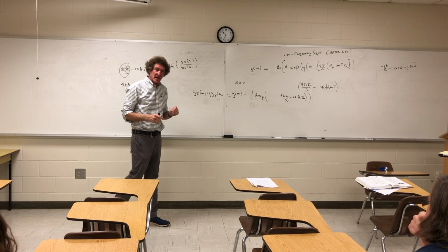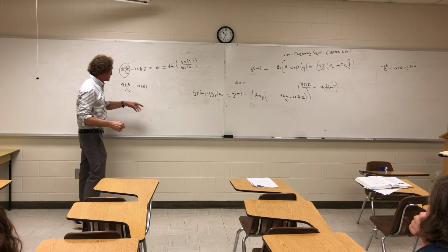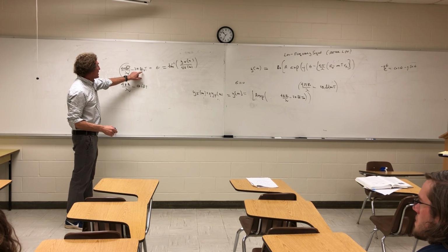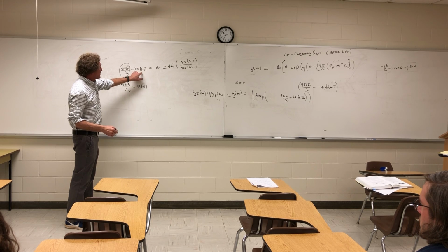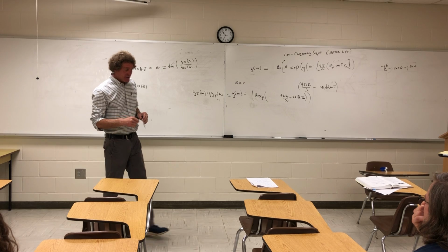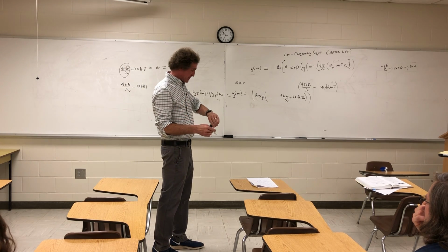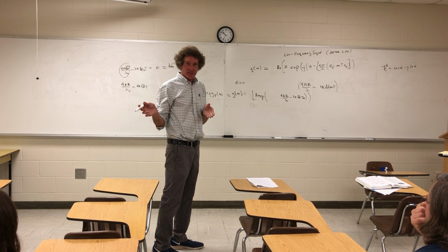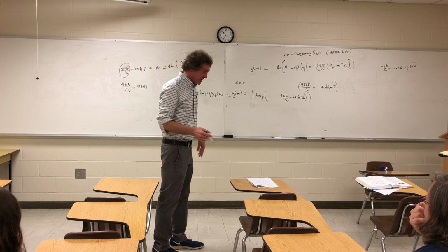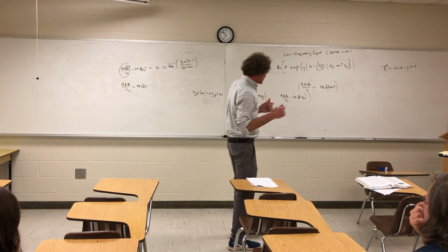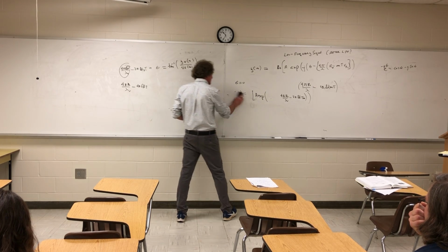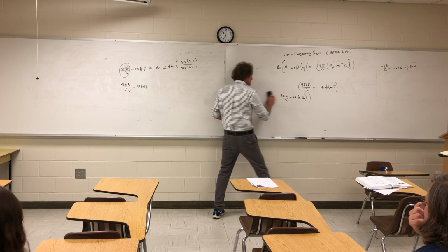So the change in that is going to be equal to 2 pi f Doppler t, and you can divide by 2 pi t and get f Doppler. Now we're going to spend more time on that later, but that's the essence of how you get Doppler frequencies. All right? You actually have to do this and realize the change in the actual range position will be felt as an effective Doppler frequency.